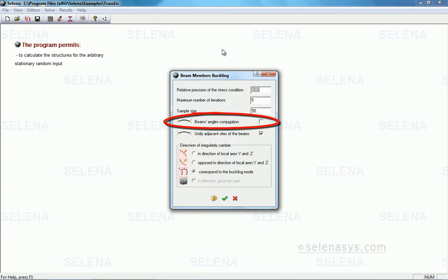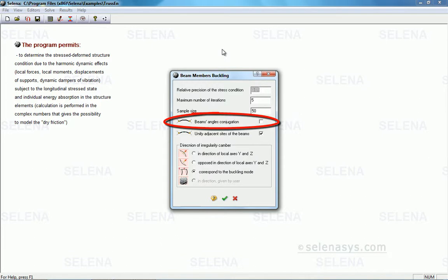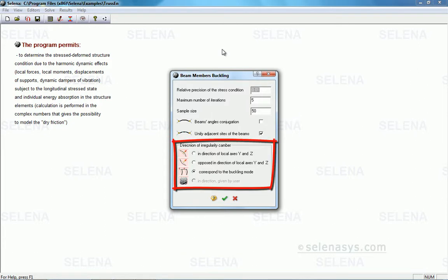The first option is to bend the rods by installation to a straight line. The second option is to include them in the construction in their natural state. The first option corresponds to the connection on the bolts, the second, to the welded connections. The flag conjugate adjacent sections makes sense to include if you have for some purpose previously divided some rods into continuous chains of segments. For the rest of the parameters, you can ignore them.